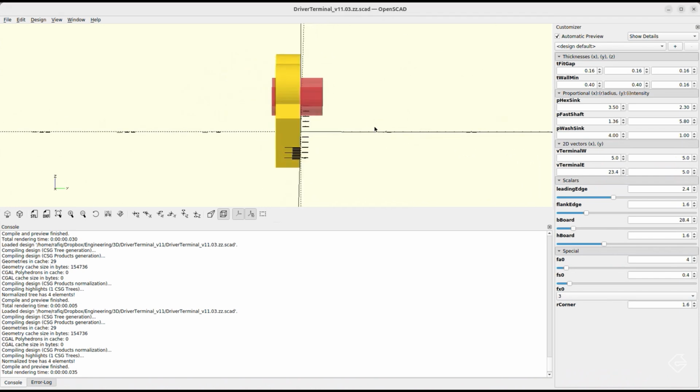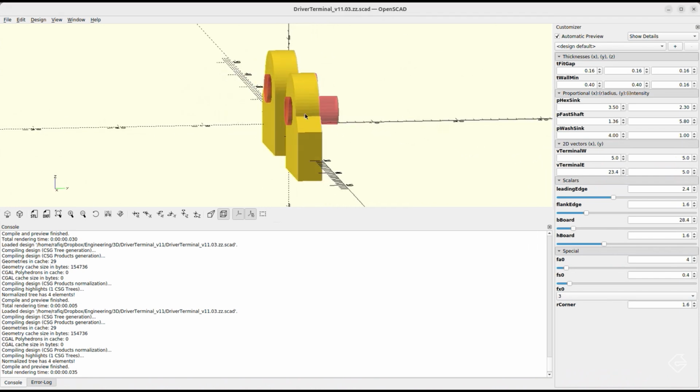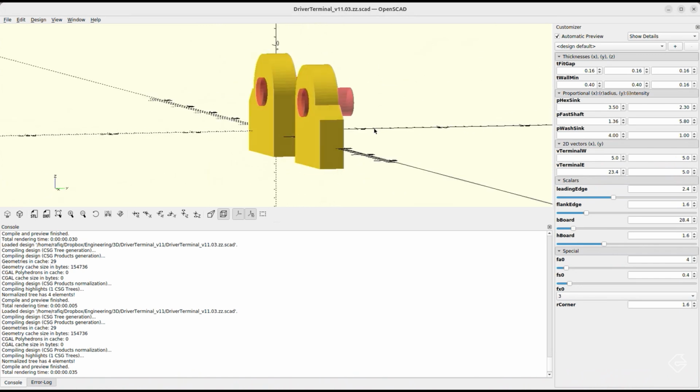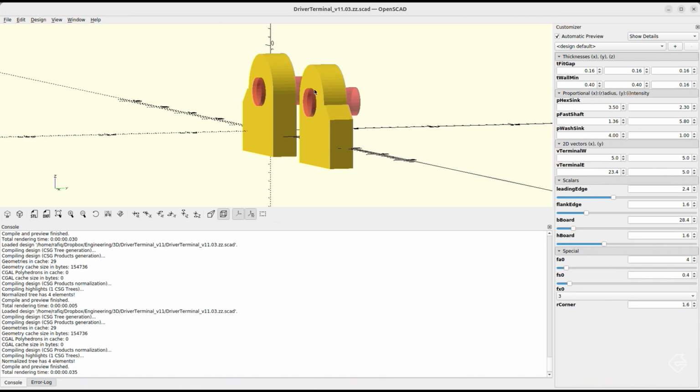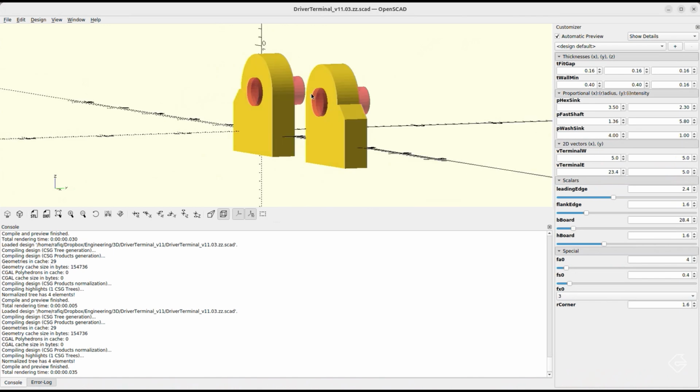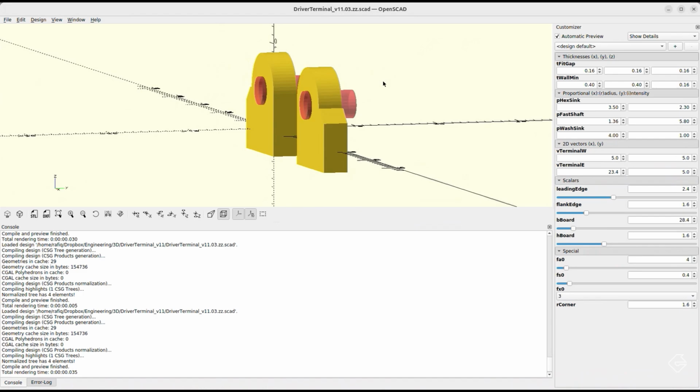notice the cylinders then adjust in this dimension, or the y-axis, to its rightful location. And we see that the portion of that fastener that actually sticks out from the end of that hex nut is not actually that much. Now, it may not be that much, but it still could potentially be some exposed metal, which we really don't want. So I think we want to be able to cover that exposed metal with some more material. So we're going to create some shaft extensions to make sure that that hole gets adequately covered.